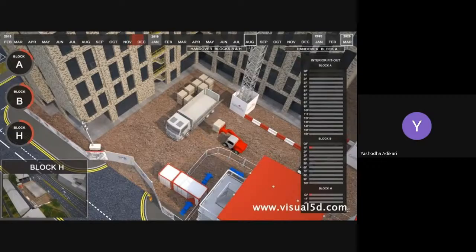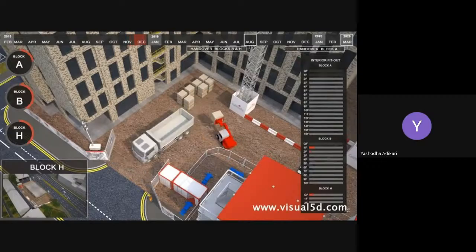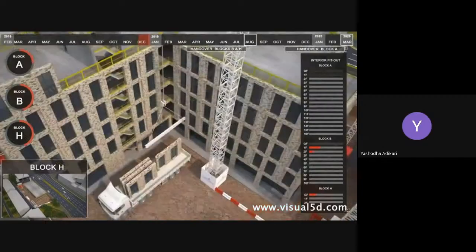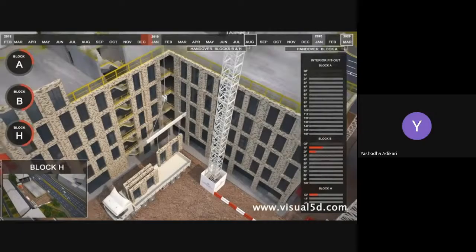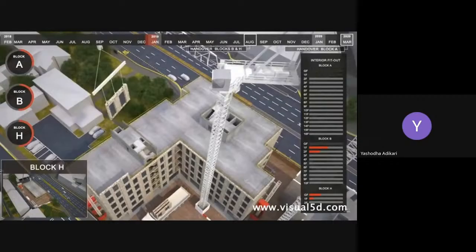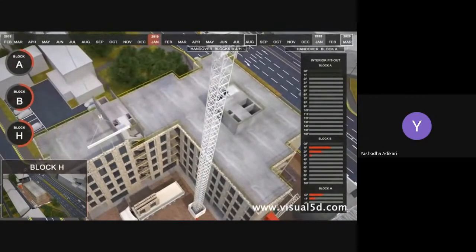Precast is up to the 5th floor. We'll commence the external facade under the podium levels and the internal fit out from the 2nd floor level. The precast units come pre-finished with the windows installed and the brickwork facade as part of the sandwich panel. This will reduce the need for major facade works.